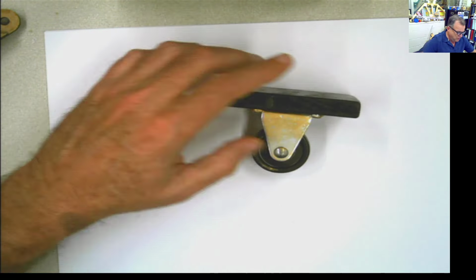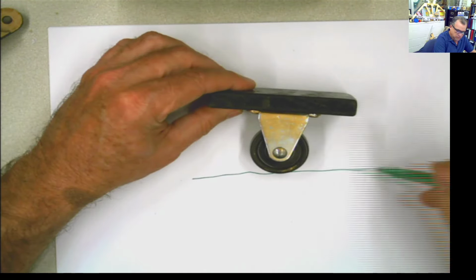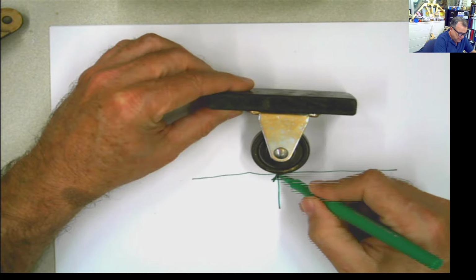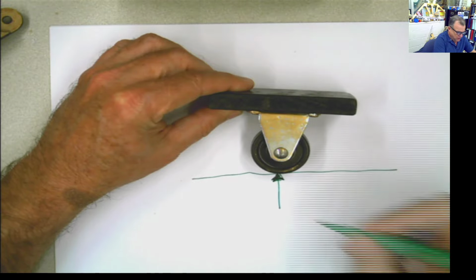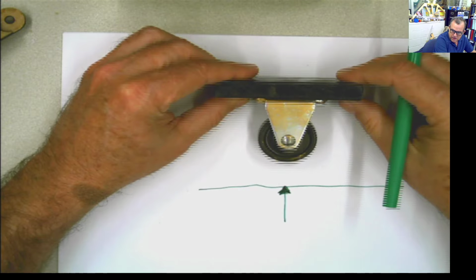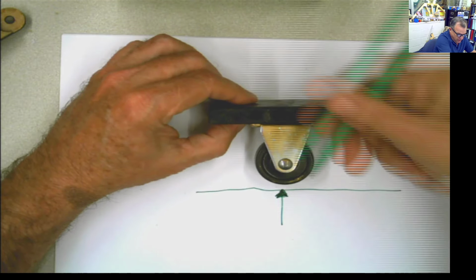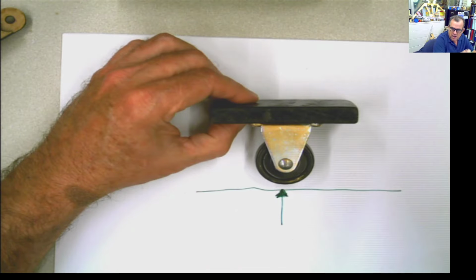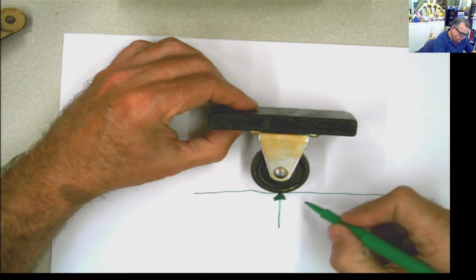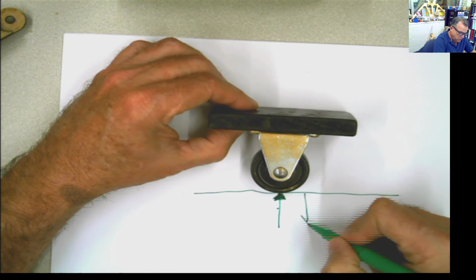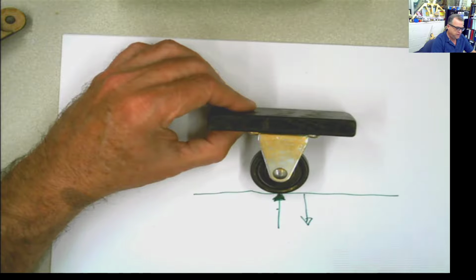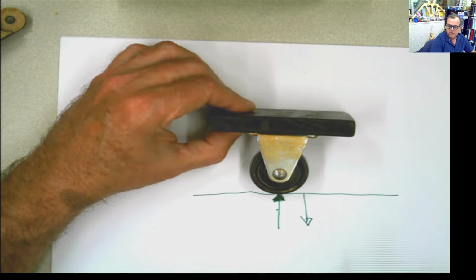So whenever you have a roller, and this is the surface, the roller is going to produce a reaction that is, and for this book in particular, we are going to assume, of course, if I get this, I can lift it, right? So that means that there's not a reaction provided in the other direction. However, for this analysis that we're doing, the majority of the rollers are able to provide either one reaction in this direction or this reaction in this other direction, perpendicular to the surface that the roller is supported by.